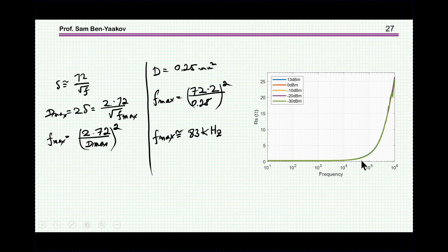But if you do have an appreciable ripple and a large AC component, then of course you'd like probably to go to a few tens of kilohertz and not even approach the 100 kilohertz. So this would be the conclusion based on this Bode 100, the Omicron Lab analysis, which is very, very useful, and without it, you really don't know what is happening.